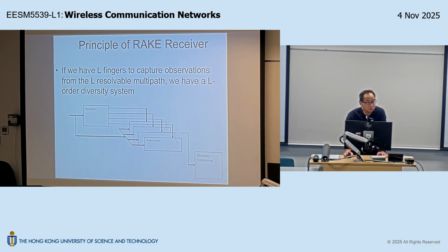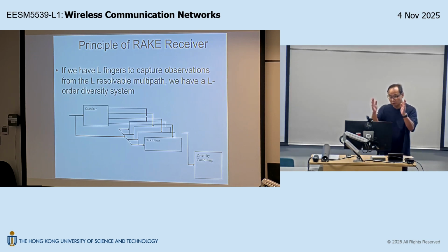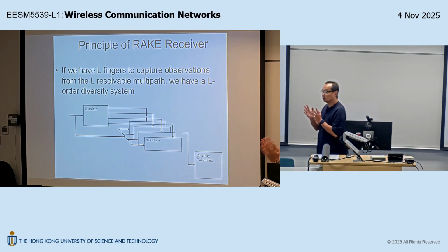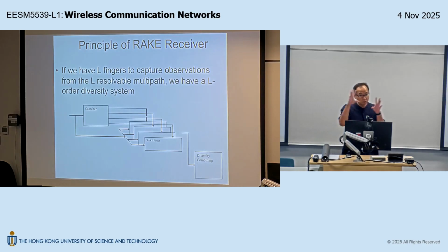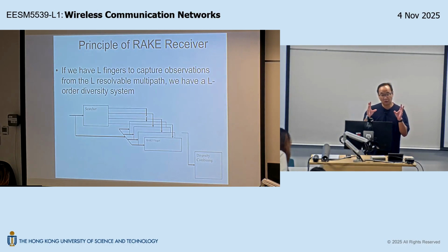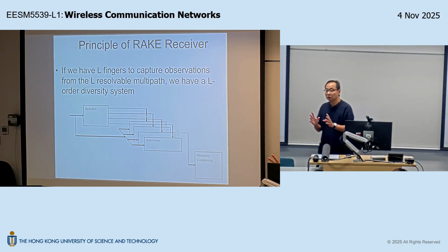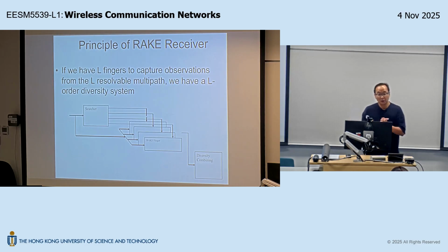So remember, by spreading and despreading, we can enjoy an interference discount factor of 1/64. If I chop a symbol into 64 pieces, then every time I come across a certain interference power, I don't need to worry about the total interference power. The only effective interference power that would affect me would be just 1/64 times the actual interference power, right? So that's the so-called interference suppression capability.